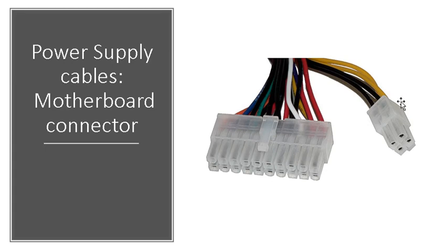So the first type of connector that we're going to be using is the motherboard connector. The motherboard connector is the biggest connector in your power supply, and it has 24 pins altogether, but 4 of these pins can be detached. So this is 20 pin, this is 4 pin. So you can detach these 4 pins from your 20 pins, and the reason for that is that some motherboards, mostly the old motherboards, use 20 pins. So this way you're supporting both types of motherboard in case you want to use a 20 pin motherboard.